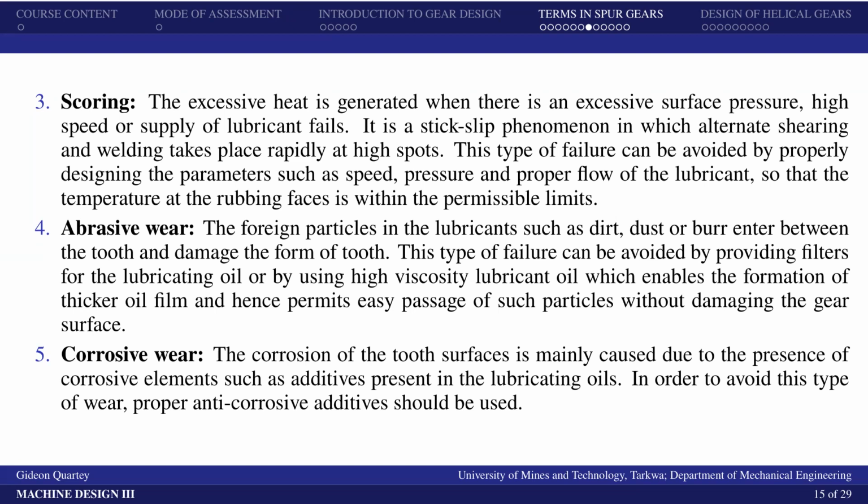Yeah. And this type of failure can be avoided by providing some filters that will filter the lubricating oil, or by using high viscosity lubricant oil, which will enable the formation of a thicker oil film and hence permit easy passage of such particles without damaging the gear surface.